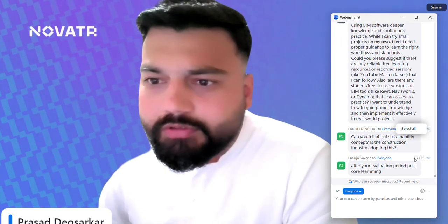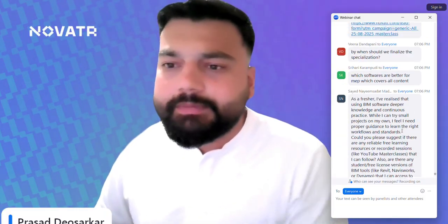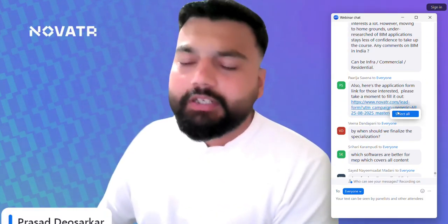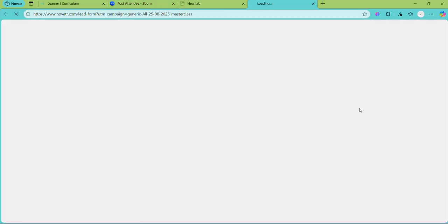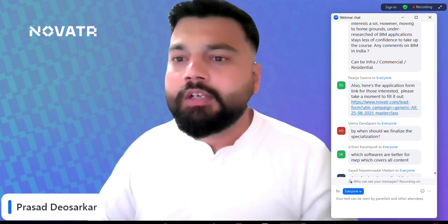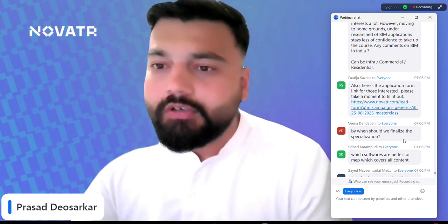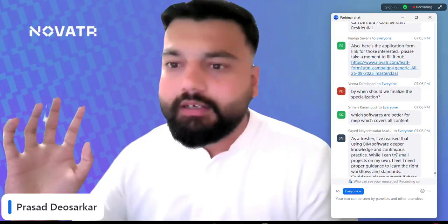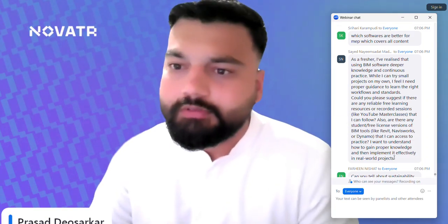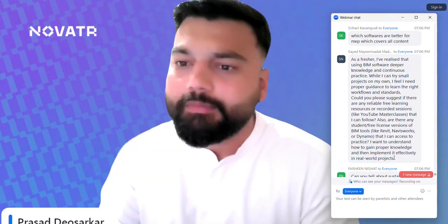So, Vivek, I think you've asked the question again. Can you learn Synchro instead of MSP? Synchro is a collaboration platform where you can link the BIM model and your MSP schedule also. You can create a schedule on Synchro, but I would prefer you to create a schedule on MSP and bring it into Synchro when you're working together with the BIM model.